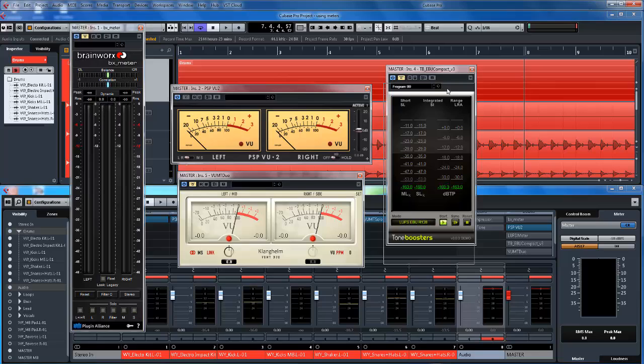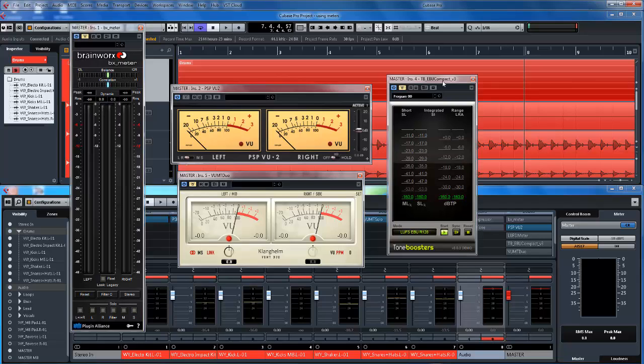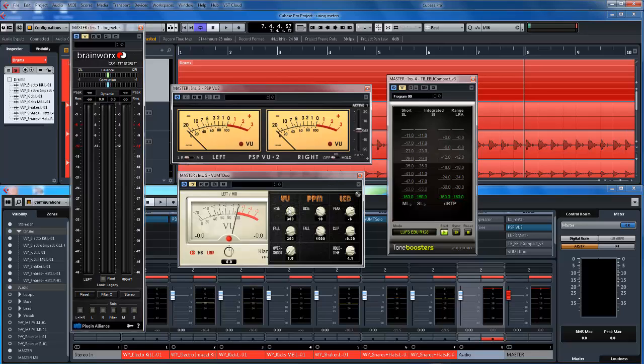So what does that mean? If you're now counting more peaks and counting across shorter and longer integration times, you're going to have levels that are different to a PPM. In other words, a true peak, trust me on this, will be about 4 to 6 dBs higher reading than a PPM. Right, now let's look at the integration time. 300, as we saw here, yes, you can alter it, but as a VU, we tend to stay with around 300.